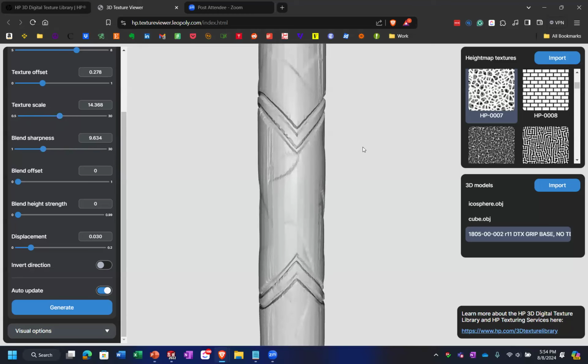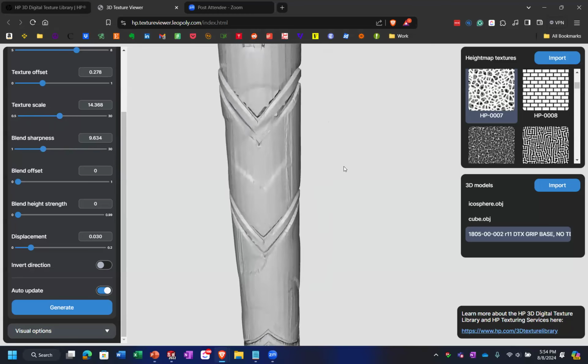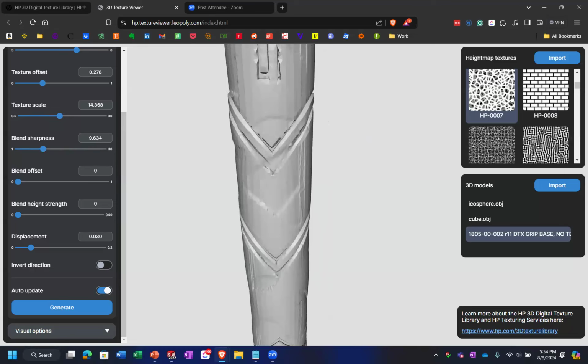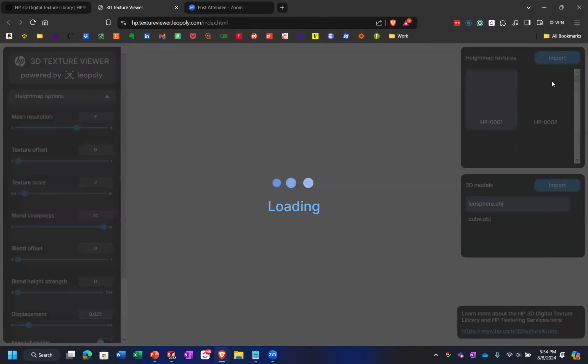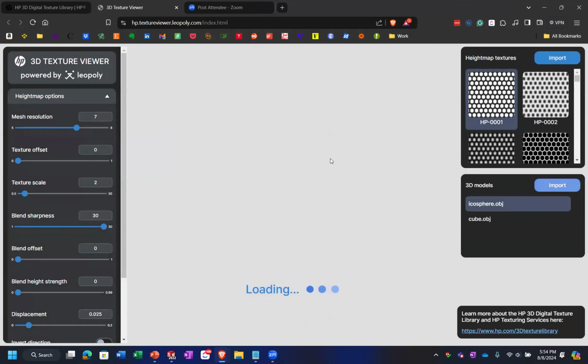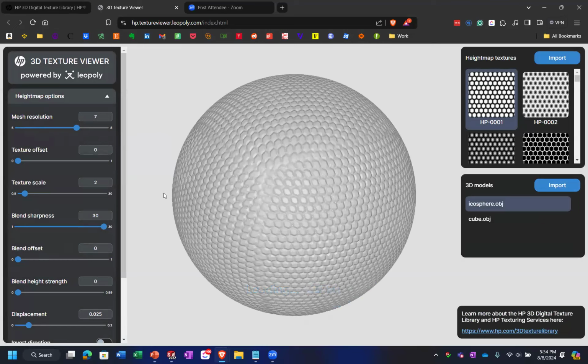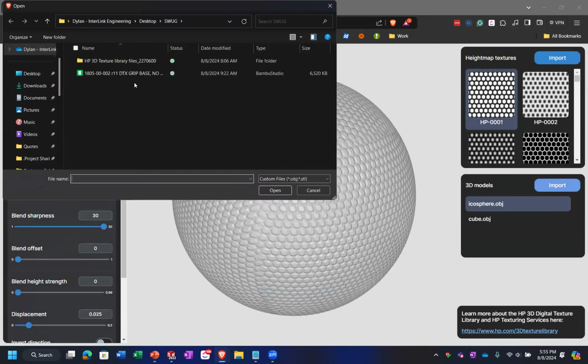You can give them the STL output and tell them just play with the textures until you feel like you've got what you want, and then take a picture of the model and the settings, because that'll be helpful reference for you. And then essentially now you know what to create for them inside SolidWorks in a more ready for manufacturing way.